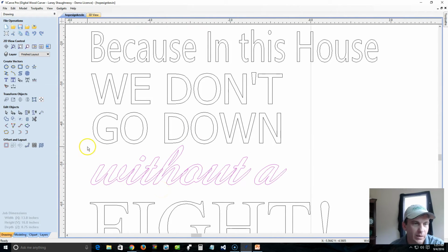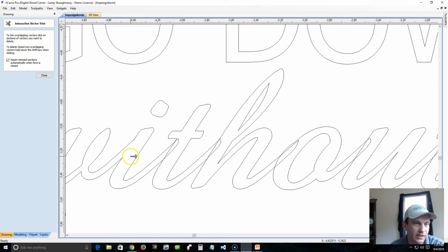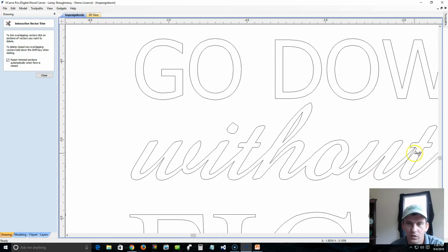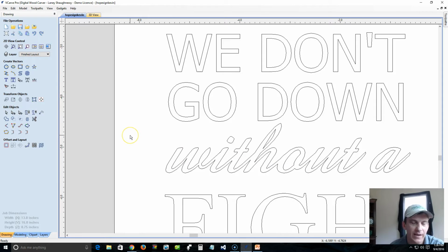So we're going to grab this, and I'm actually not going to use the weld tool for this one. I'm going to use the interactive trim, the scissors tool, so that way you can kind of get a feel for that as well. So we'll go ahead and convert that to a curve. We'll turn on our interactive trim tool. We're going to click this outside line first. There you go. There. There. That. And one last one to achieve the same results. Okay? So there are a few tools that are available to us that get us to the same end game, the same endpoint.